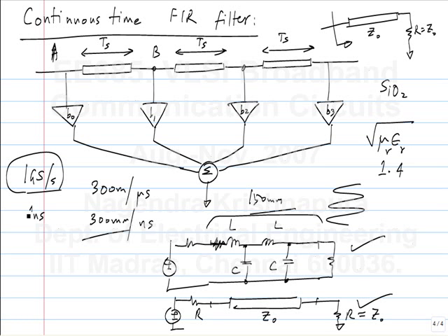Now if I make it with transmission lines, what do I have to do? So basically it is not really possible, right? We can't easily tune the delay of the transmission line. A delay of a D flip-flop is defined by the clock edge, whereas the delay of the transmission line is defined by the length and so on, which we can't change electronically. So if you are operating over a range of data rates, it's also hard to adjust this.